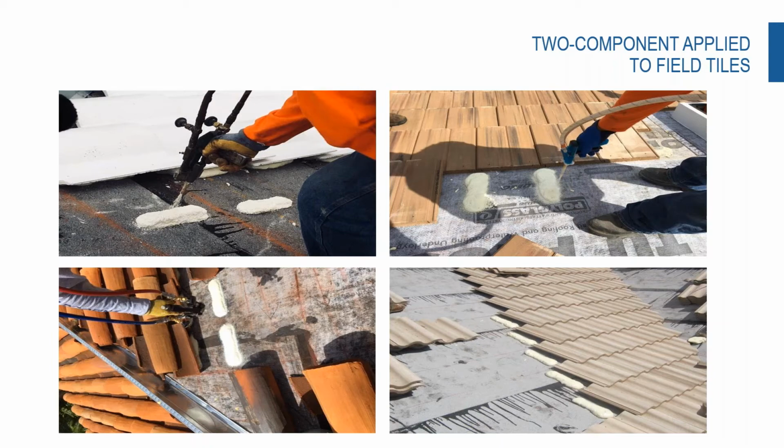For the metal gun, it's durable, it can last long, but you have to have a good maintenance crew to maintain the parts that are associated with that. If it's a job that you're doing adhesive and you're not going to do a job for a couple months, you might gravitate more towards the plastic gun hose assembly. And as soon as you're done with that, you throw it away and you can attach a new plastic gun hose assembly for your next job.